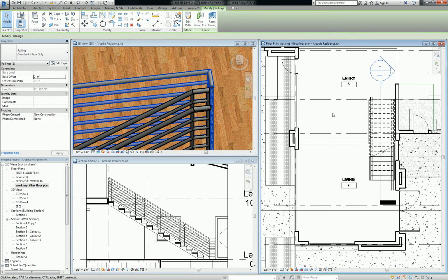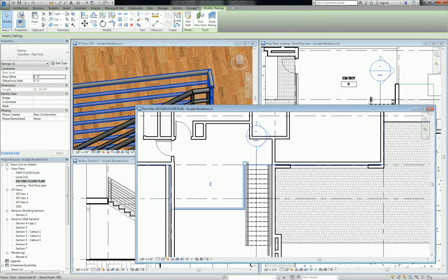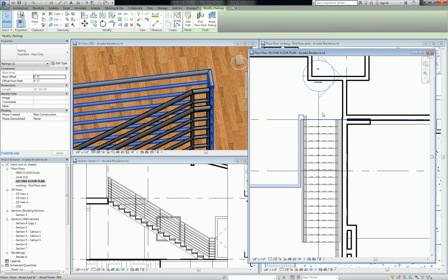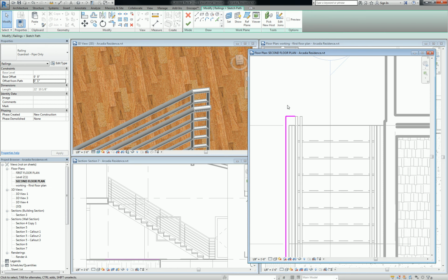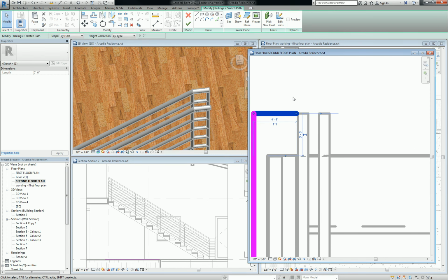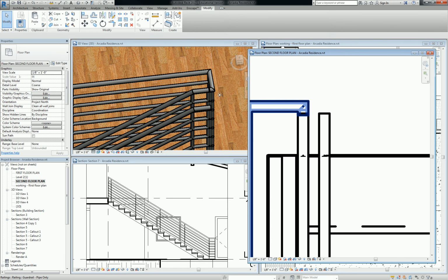I told you that, oh, I gotta open the second floor. I told you guys that the handrail family, or the guardrail rather, might have to make some funny little connection concessions. Well, that actually just looks like this. I'm gonna edit this path, and what I need to do is turn this path down in order to create that corner. So it doesn't matter what it is exactly. I just go to that edge and I turn it back. I could even just do a 1/4 inch, something that's barely even visible, and hit check, and it's going to turn back and connect.